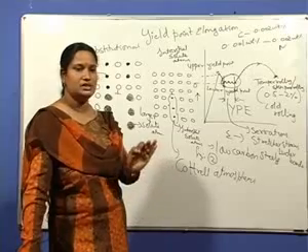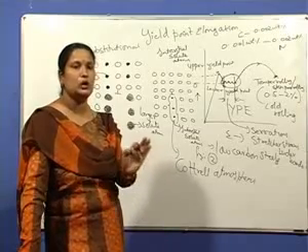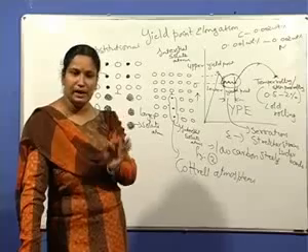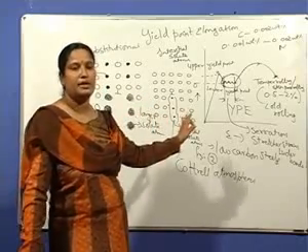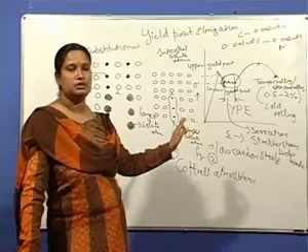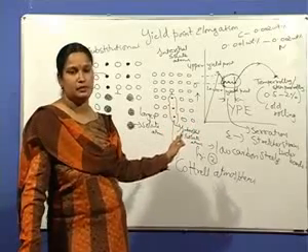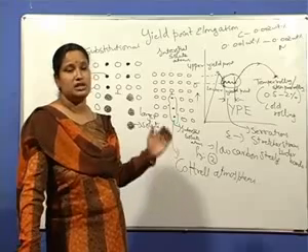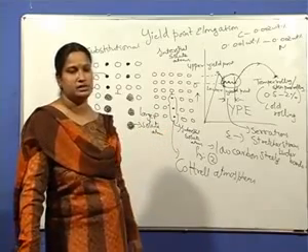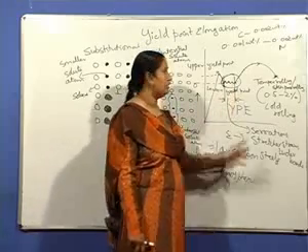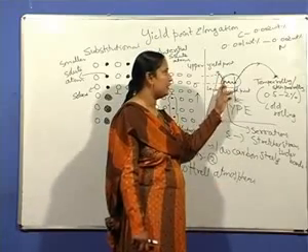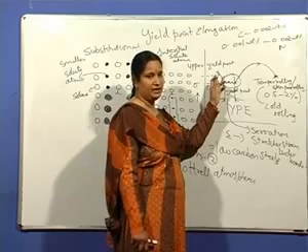The main reason for the yield point elongation seen in low carbon steels is the interstitial solutes, carbon and nitrogen, which form atmospheres, Cottrell atmospheres. The dislocations are locked by these atmospheres. Thereby you have this yield point elongation, where the stress suddenly drops at point A, known as the upper yield point.